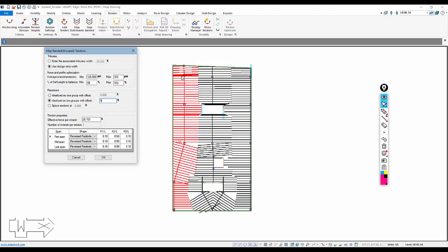The program will replicate this exact support line. So one of the tendons potentially could actually fall outside of the slab. That's the first thing. And also the tendons will replicate the spans. So there's going to be 1, I'll mark these. There will be a cantilever span, I'll call it cantilever top. And then there's going to be span 1, 2, 3, 4.